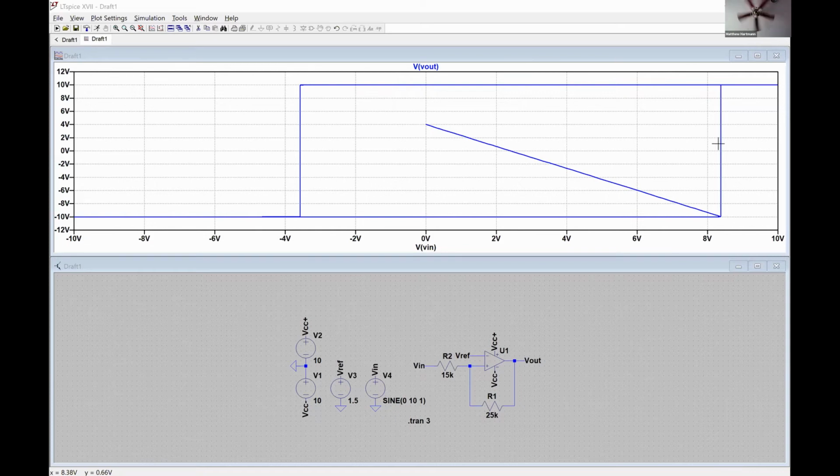Okay, so for this particular problem, you could give me a hysteresis loop like this for your result, or you could give me the time domain plot where you're plotting the input signal and the output signal together versus time. As long as I can clearly see that it's triggering to the positive limit whenever you're at or beyond your upper trigger limit, or whenever it goes down to your lower trigger limit because your voltage is less than or equal to the lower trigger limit, I'm fine. It doesn't really matter which way you show it to me.